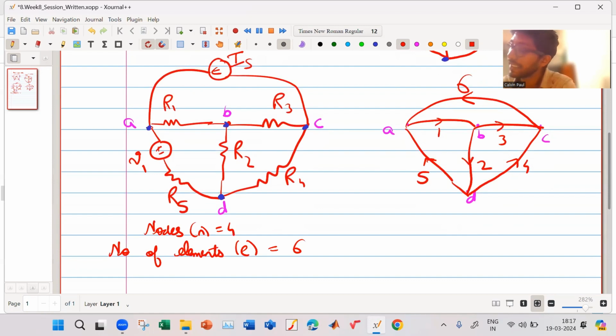All right. Then one more thing is each of these will have some particular voltage and some particular current through each element. Let us consider element 1. It has some voltage and some current. So this is your current direction. Then your voltage notation in terms of graph theory, this will be plus, this will be minus. So this will be VE1. Your current is flowing from the point of higher potential to lower potential. Yes, sir. So this is your VE1.